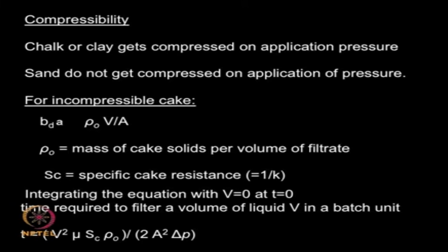And if you assume the specific cake resistance as the capital sigma C, which is equal to 1 by K, K is your constant which I defined in Darcy's law, then we will end up integrating this Darcy's law by assuming at t equal to 0 the volume that is filtered is 0. By doing that we can get a relationship for the time required to filter a volume of liquid V in